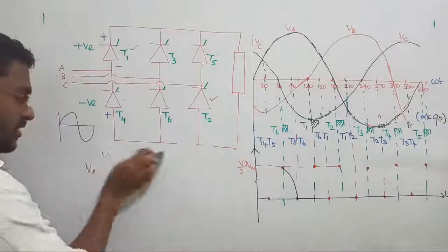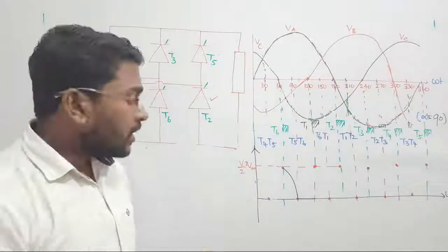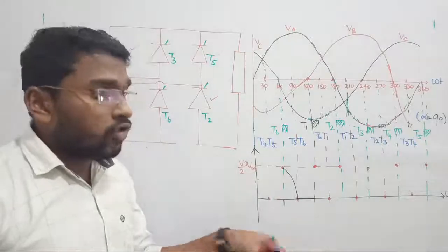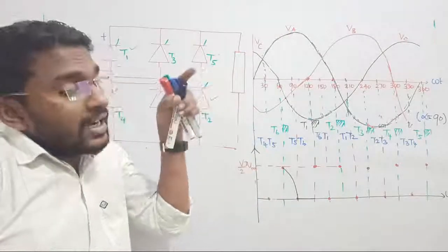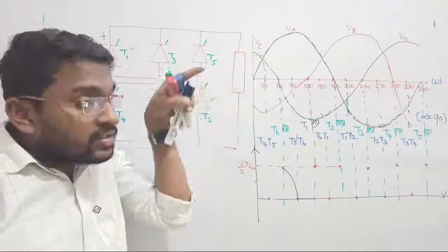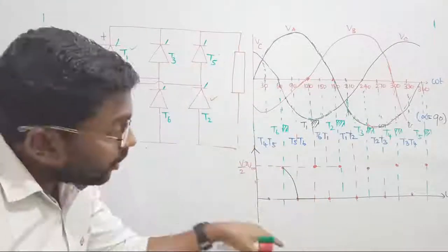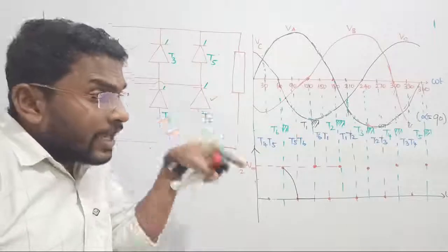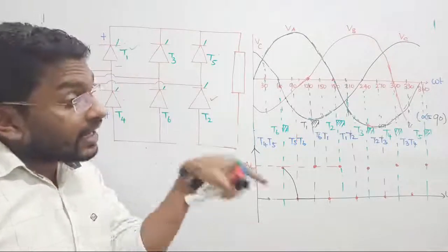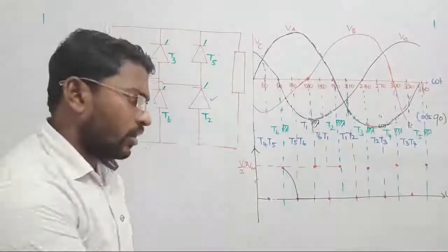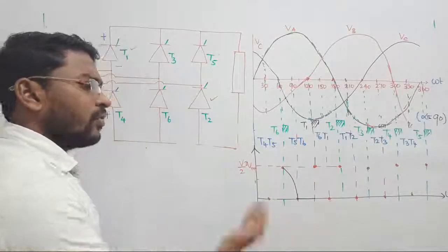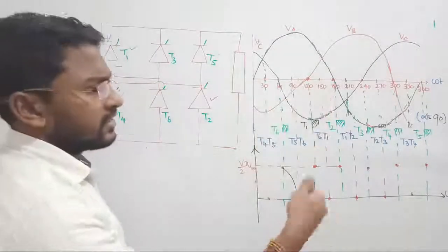In continuous conduction, for whom will it occur? Discontinuous conduction will occur for a resistive load. If you have an inductor load, then the inductor will freewheel and push the thyristor to continue its conduction even in negative voltage. So the negative spike will exist when we have inductive types of loads. Let us continue, right? I don't want to draw the discontinuous right now. Let me completely draw the waveform and then we will remove the negative spikes by considering resistive load.